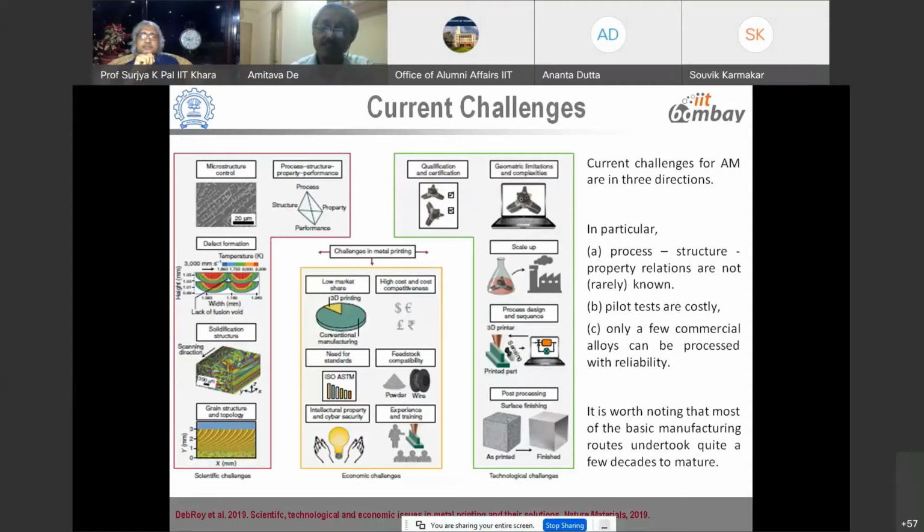Now the problem here is that these granular level changes, difficulties or features are happening in a layer by layer manner. Imagine we are starting with a powder scale, with powders of size in the range of 100 to 200 micron. I am talking in a bigger sense. In many cases powders are even smaller than that. With that scale, we are thinking of building a layer of two powder heights, for example, 200 micron or so. And every such layer, every such track, for example, would have this kind of differences.